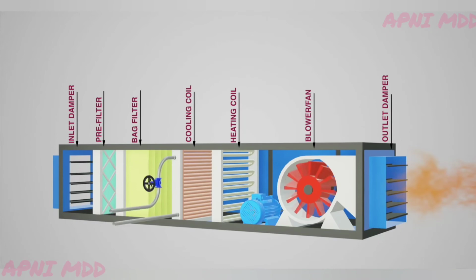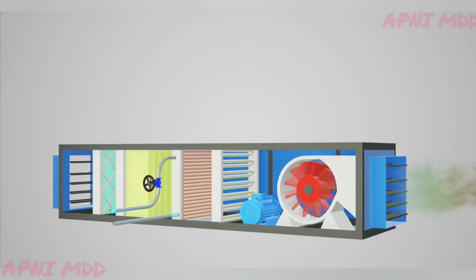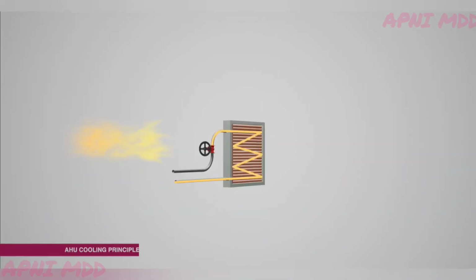In simple terms, AHU takes outside air and pushes it to the building spaces while conditioning the air with required cooling or heating as required by the building occupant. Basic idea of AHU is, when the space temperature goes high, the valve on the return side of the cooling coil will be opened to provide more chilled water or refrigerant gas to the cooling coil.